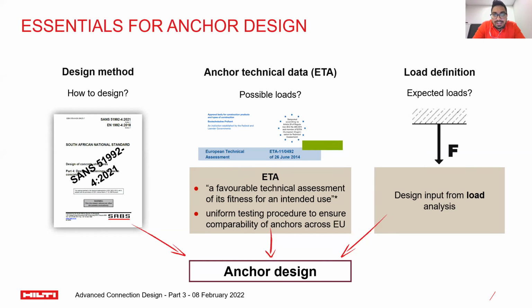Together with that, you'll need anchor technical data, which is based on an ETA. So the ETA is a third-party organization that does technical testing on our anchors in line with Eurocode 2 Part 4. You have to have this in order to do an anchor design. And then from your side as engineers, you will need your loads. So any sort of actions and reactions acting at the connection, you will need to define those, and together you can do an anchor design.